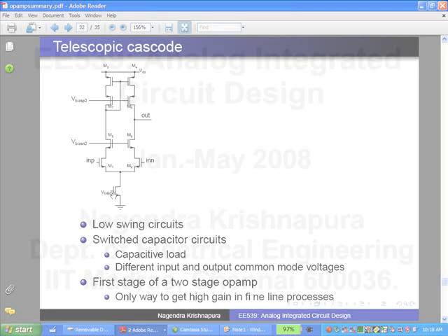So, as usual, you have a trade-off between accuracy and speed. For accuracy, you need longer devices. That is, you need higher DC gain and lower offsets, right? For both of these things, to get lower offsets, lower flicker noise and higher DC gain, you will need longer and wider devices, which goes against getting high speed. This is always a big trade-off. Okay.